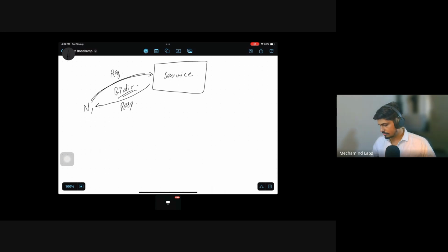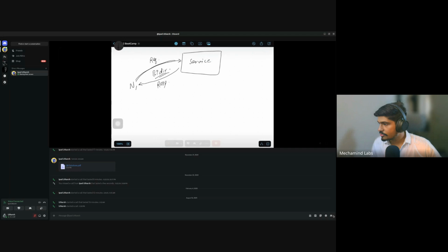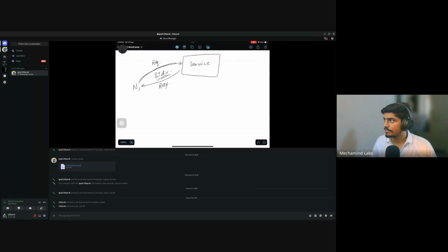Okay. So this is what a service is. Just like topics had their own message types or interface, the language in which they communicate, similarly services also have their own language, the request-response system, in which they communicate. For example, a service is meant for accepting requests only as integer data. It will not accept a request as string data. It will accept a request as integer, but it is supposed to respond in string, so it will respond in string.